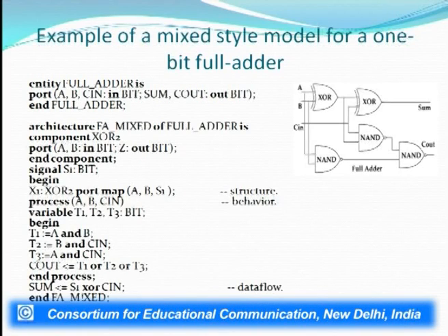It is always preferable that structural programming be used wherein one component is being repetitively used. For example, here the XOR gate has been used twice, so one could have easily called it twice, one to generate the first output and the second to generate the second output.